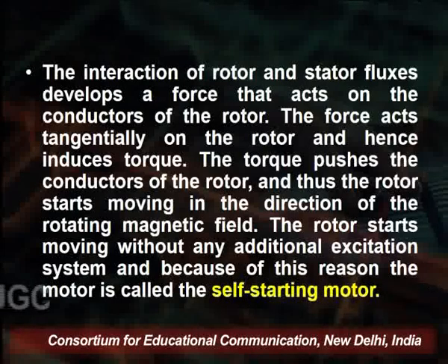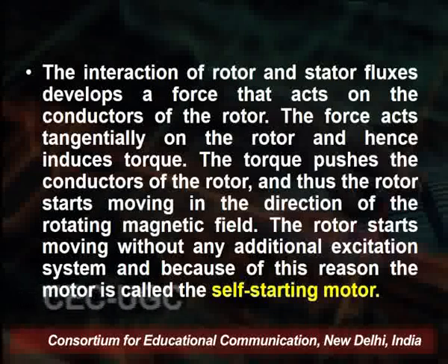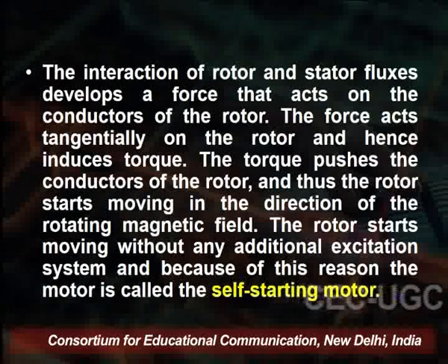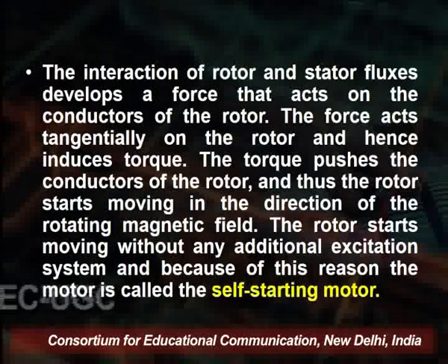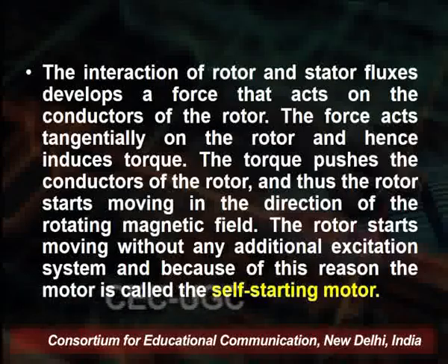As there is interaction between the rotor and stator, flux is generated, and that flux generates the force that acts on the conductor of the rotor. The force acts tangentially on the rotor and hence the induced torque is produced. This torque pushes the conductor of the rotor, thus the rotor starts moving in the direction of the rotating magnetic